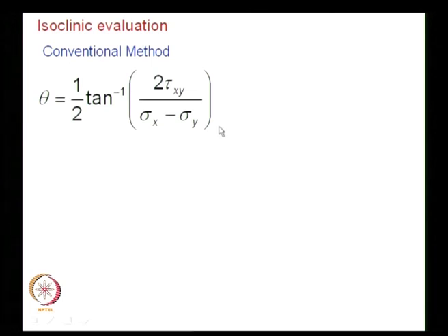If you know how the Mohr circle is drawn and how to interpret it, you will be able to fix that the theta I have calculated corresponds to the sigma 1 direction. The theta I have calculated plus 90 degrees will give me the sigma 2 direction, and normal calculation you do not require at all, so you do not worry about it. And when I use this standard analytical expression, this expression cannot give it. So, you need to do something extra.